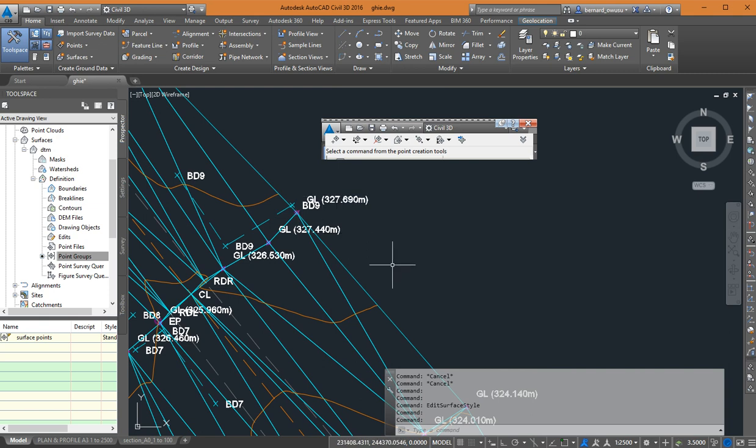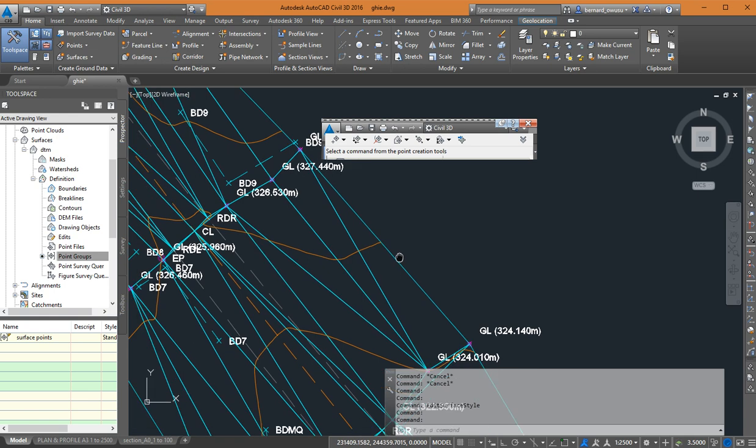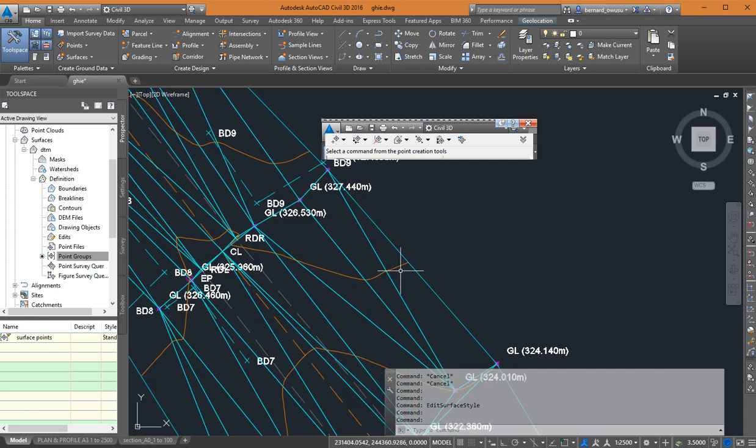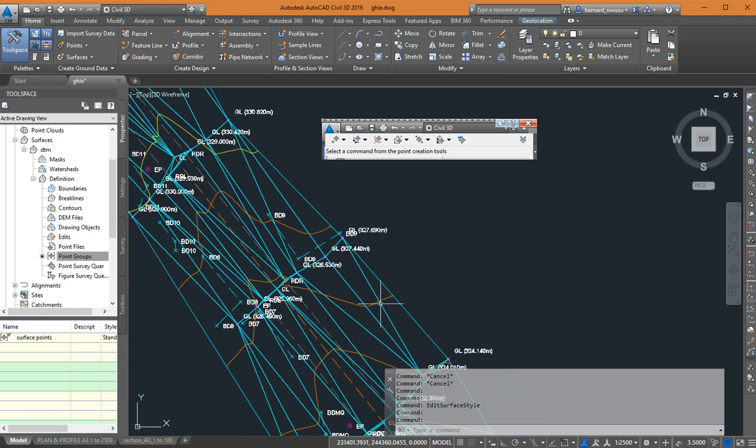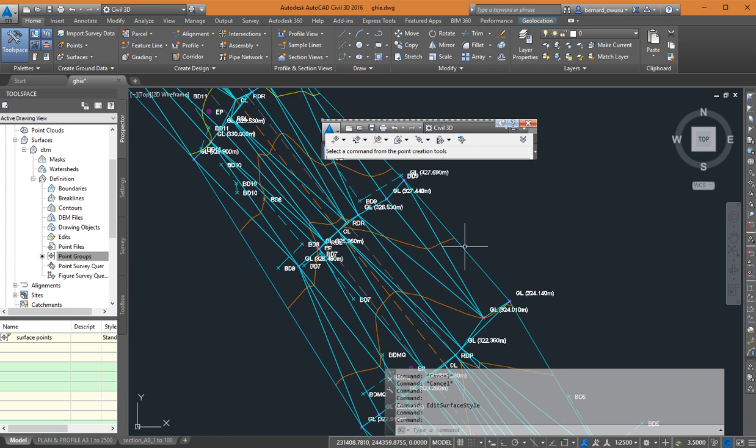327 point something. So it means that this elevation, what is it? 325 or something. This, so 325. It's between 324 and 327. You can get a 325 somewhere. So if you recall it, if you did survey, the contours basically connect points with what? Equal elevation. So it means that there's 325 here, there, and you connect it to form this contour line.